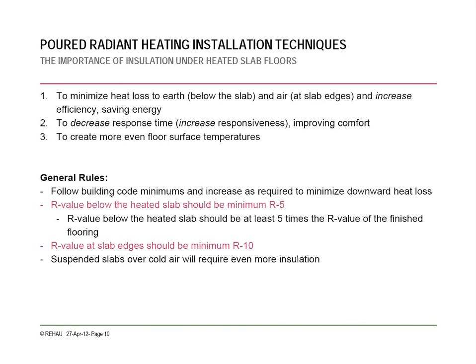For minimum, as you can see here, they're showing R5 below and R10 on the sides. There are other types of insulation as opposed to a standard foam insulation, such as CoverTech. If you've ever done a job that TEC's worked with, we'd use a lot of the CoverTech R foil insulation, which is like a poly with a foil layer. Those don't necessarily have as high a traditional R value. I think it's usually like 3.8, but they have an aluminum reflective barrier, which helps. So in either case, you do want some form of insulation.